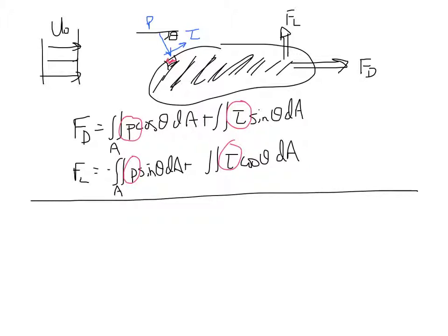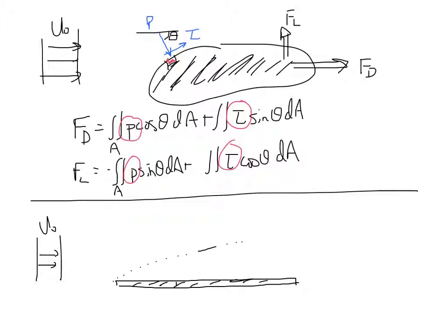The first case that we started talking about today was the flat plate and the boundary layer that develops on the flat plate. So if we consider a long flat plate, here's a solid plate, again approach velocity u0, the sketch that I wanted to set up for the boundary layer that develops is a region adjacent to the plate that experiences the frictional effects of the plate. That's going to be our boundary layer. The boundary layer is described by boundary layer height, delta of x. We talked about three different ways of calculating that boundary layer height today.